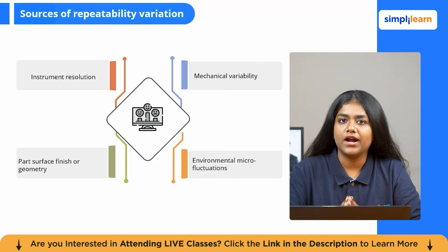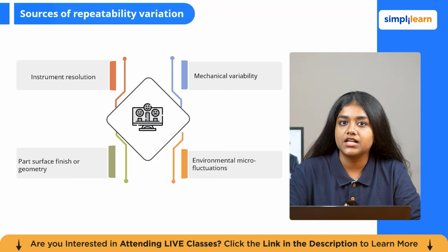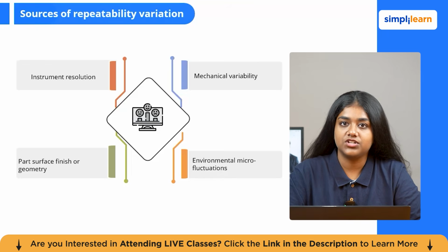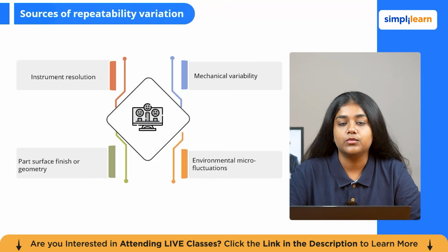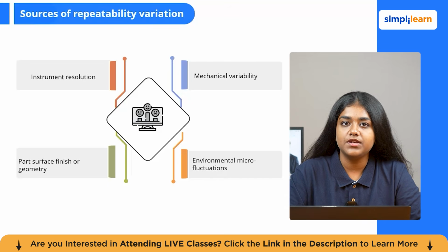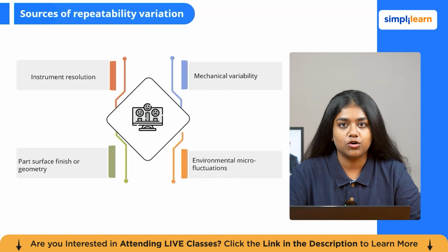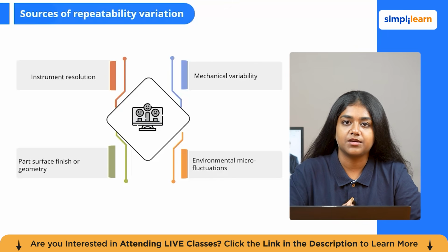So you might wonder, why does repeatability matter? If repeatability is poor, it means that the gauge itself is inconsistent. Even a single skilled operator can't get consistent readings. That's a fundamental problem with the instrument, and no amount of operator training will fix it. The instrument needs to be repaired, replaced, or reconsidered. The consistency of the same operator is the baseline test of instrument capability.